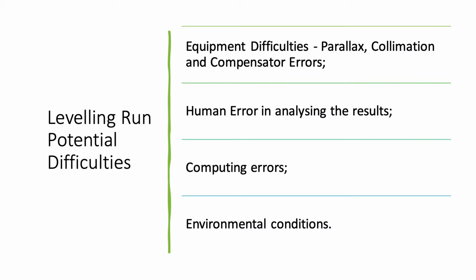5.4170 meters. Potential difficulties when carrying out this task include equipment difficulties in terms of parallax, collimation, and compensator errors, human error in recording and analyzing the results, and environmental conditions such as noise when recording results.